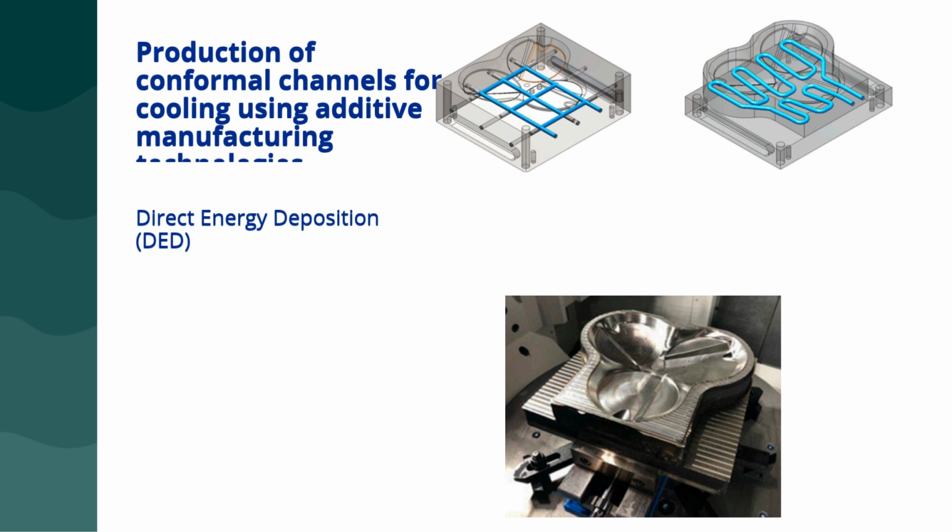What does this mean? It means that when we perform simulations to optimize cooling for complex parts with large volumes, we can predict intricate cooling channels. In traditional approaches, we often drill injection molds, resulting in straightforward channels for cooling. In contrast, conformal channels can take on complex 3D shapes, which can be more efficient.